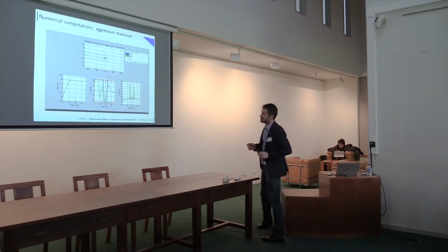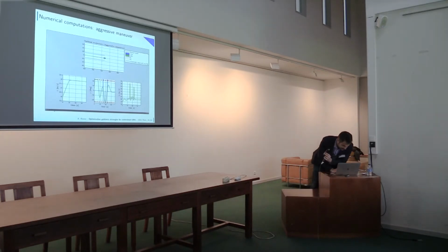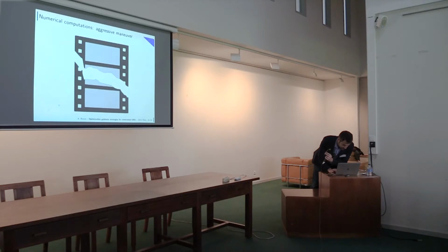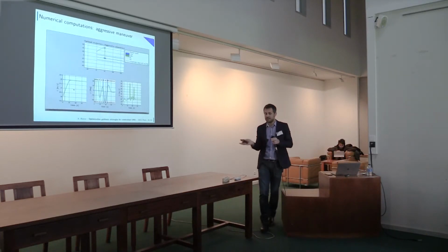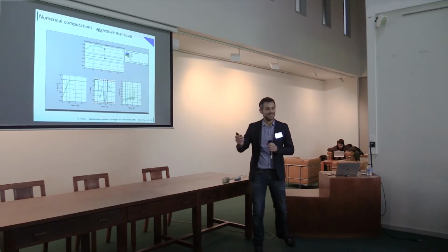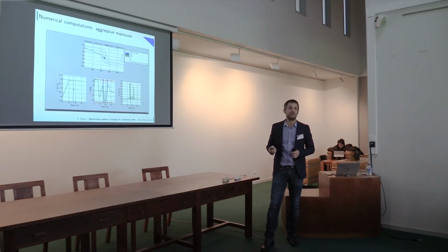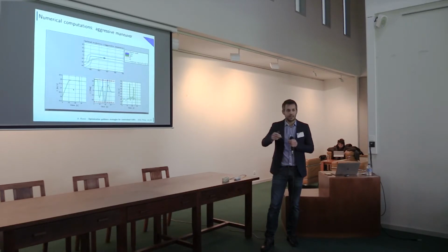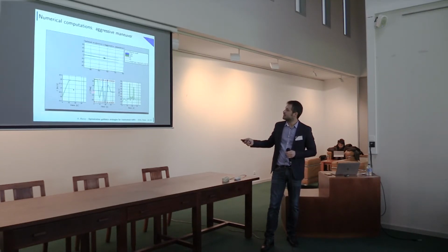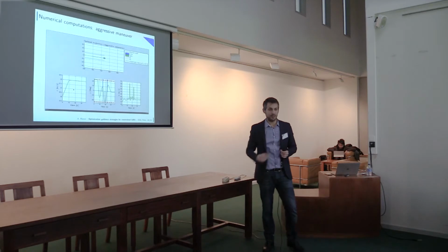And here it's interesting to see that when there is a turn, the right turn and the left turn, the virtual vehicle is going fast. The green one is the actual vehicle, our UAV model, and the blue box is the virtual vehicle. You can see this yellow line is the lateral error, and this other line is the longitudinal error between the UAV and the virtual vehicle. And here you see that the roll angle is constrained at the beginning because you want to approach the desired path and so on.